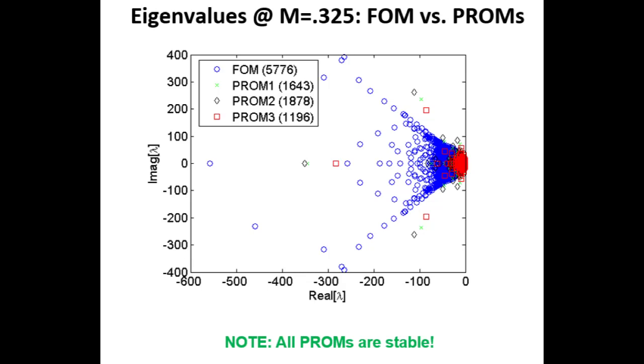Note that the sizes of the parametric reduced order models are relatively large compared to the size of the full order model. This is because, as said earlier, in compressible flows, Mach number plays a very important role affecting the entire flow, particularly in transonic zones. This is in contrast to our Goland wing model, where we only had a localized parameter variation. Instead here, we have a global effect from the Mach number. In the perspective of gauge modal invariance, which will be expanded on in part 3 of the video series, the PROMs are relatively large to capture richer gauge symmetries in the flow field.